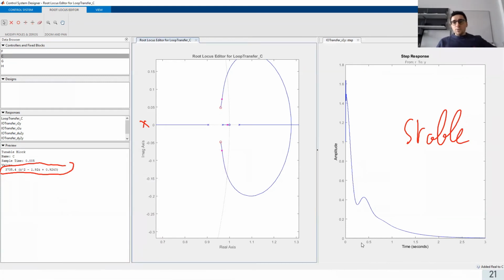So basically, the fact that we are approaching 0 means that for the system we add 3 poles, 4 poles, and now we have 3 zeros. And so here it just means that the static gain of the system is 0. When you have this kind of behavior in continuous time, it's called a differentiator. So the static gain is 0, so the output is non-zero every time the input is changing.